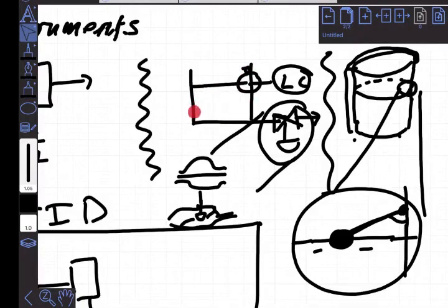Do we have a physical kind of a bunting, some kind of a thing that the tank can flow over into? Are there alarms placed along the top of that tank limit that will alert personnel that a high-level situation is about to occur? So in other words, the level controller can only do so much in terms of maintaining that level. There's a whole other system outside of that, which is called the interlock system or alarm system, right?